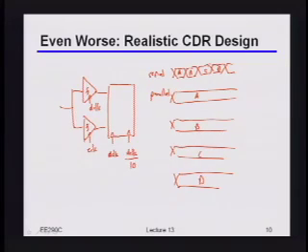So typically then what will happen is you'll take all of those parallel things, and rather than just doing all the same computations you would have before, you'll just look for some aggregate behavior. So you might say, okay, let's say I do a divide by 10. I may have had 10 possible up and down signals, right? So what I may do is say, only if I get more ups than downs across that whole window, only then will I actually move up, right? Or maybe only if I got 2 more ups than I got downs, only then will I move up, right? And so on and so forth.